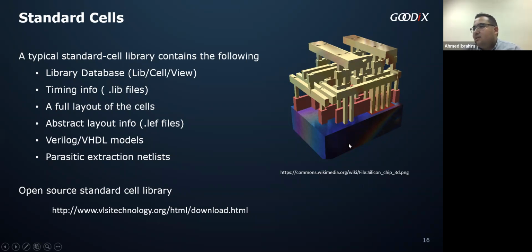So what is a standard cell? It is a pre-characterized, designed, characterized, small design, usually a digital block, logic gate, or other. It's shipped with complete info about schematic and layout, and can be placed directly, manually I mean, in analog flows, or by PnR tools in digital flows.